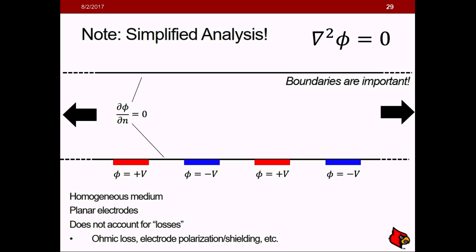So you have, say, positive and negative, 0 and 180 degrees out of phase potentials applied for an interdigitated electrode system. If you want to study the boundary effects of your system, make sure that you have a healthy distance between your electrodes and an insulative wall far downstream. Otherwise, these boundaries are insulative, so the electric field is obviously not going to bleed through those walls. It acts like a mirror, and you have the same geometry on the other side.